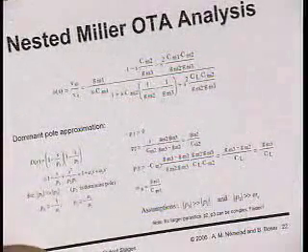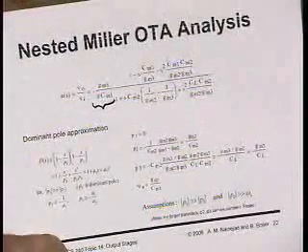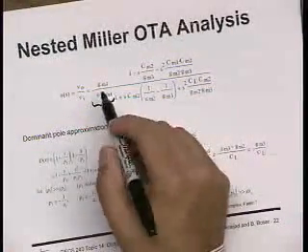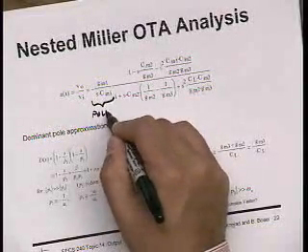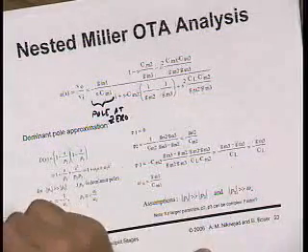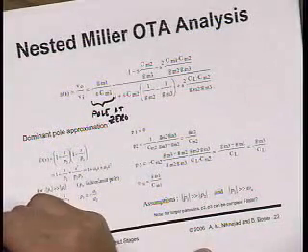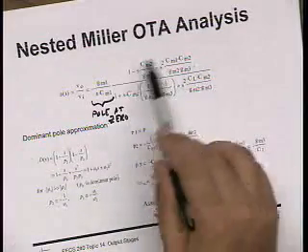And the transfer function, first of all, as you would expect, has infinite DC gain, right? And it has a pole at 0. That's exactly due to what we just talked about, the fact that we got rid of all the resistors. And then it has a couple of poles here. And it has a couple of zeros.